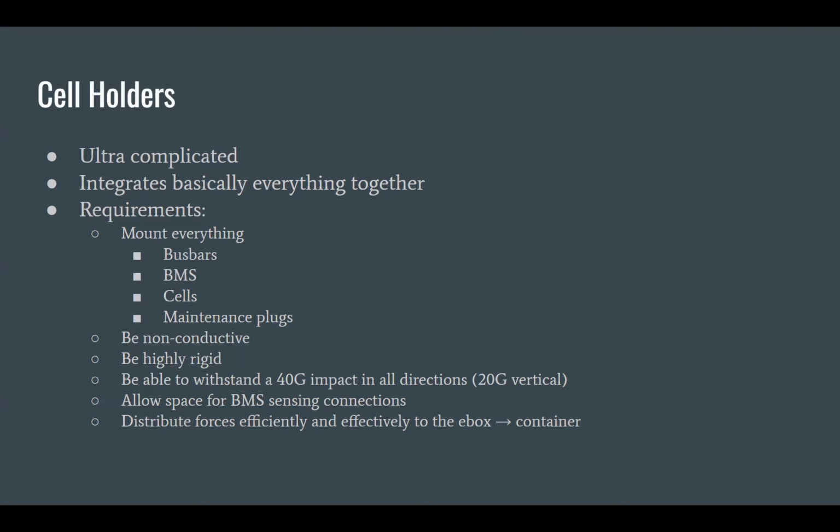The other big requirements that they have, which I think are sort of implied but I will highlight anyway, is that they need to be non-conductive. Because it holds the battery cells directly, the battery cells are exposed electrically conductive surfaces. If you put two cells together into a metal cell holder, you would short all the batteries together, and obviously that would explode. That'd be bad. So the big thing is it needs to be non-conductive.